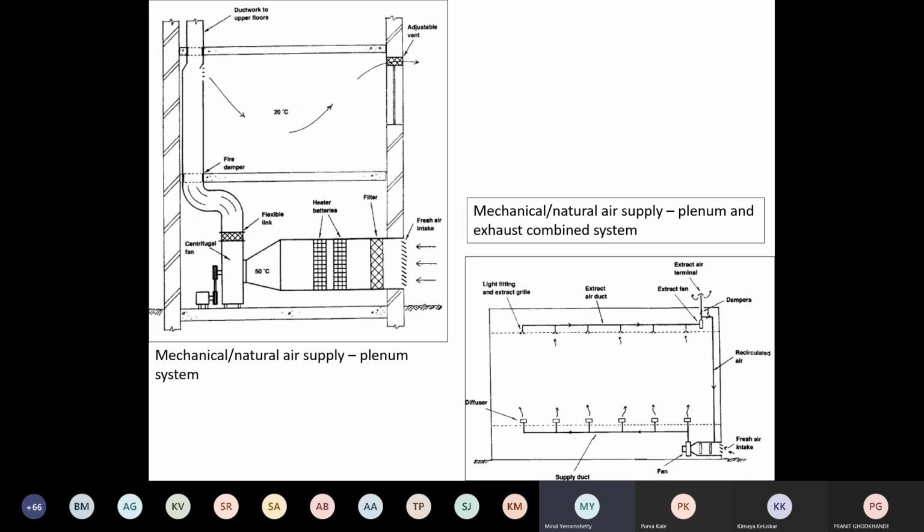So in such a scenario, any which way I cannot have it out, and I need to bring it out, and I have to be at least 3 feet above my ground level. Position my duct in such a way, higher the better, but I'm giving you minimum as 3 feet. Don't keep it at the ground level.